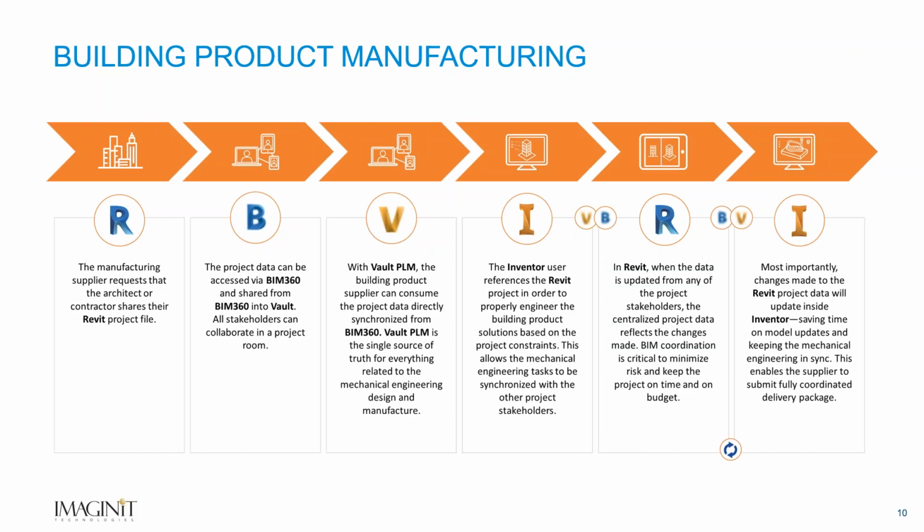Go ahead, Brian. Yeah, and I think that's really important to talk about how I can get a Revit file from Inventor here. A lot of the Inventor information is going to have a lot of pieces of geometry, a lot of detail in there. I don't want to just blindly bring it into my Revit project. I get more control when I'm linking that information in.